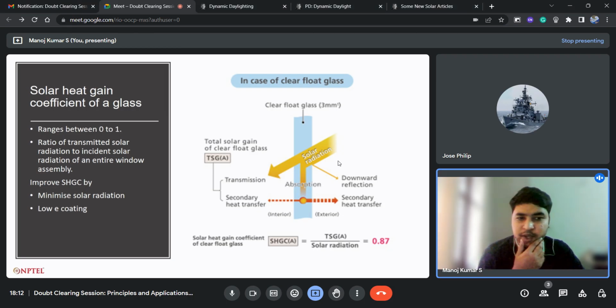We have to decide according to the climate and the solar geometry, for this site, this context, this particular room, whether I need a larger or smaller opening, double glazed protection, and whether I need solar radiation inside my space.